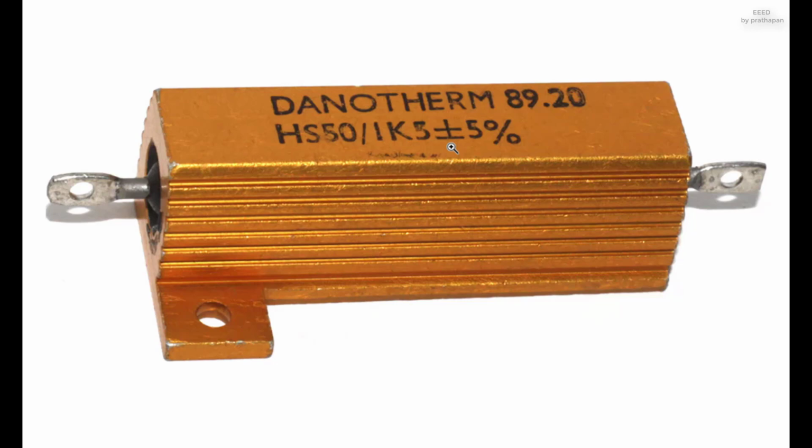Since poor air circulation, high altitude, or high operating temperatures may occur, resistors may be specified with higher rated dissipation than is experienced in service. All resistors have a maximum voltage rating. This may limit the power dissipation for higher resistance values. An aluminium encased power resistor rated for dissipation of 50 W when mounted on a heatsink.